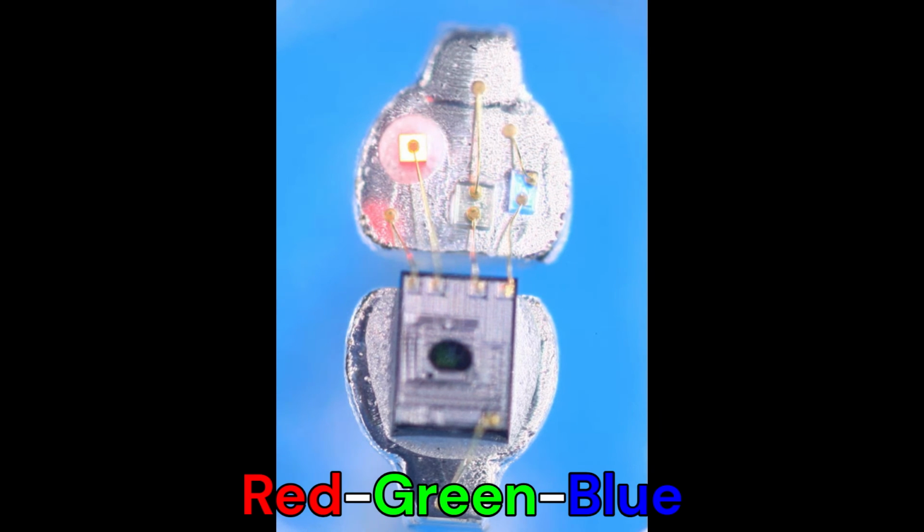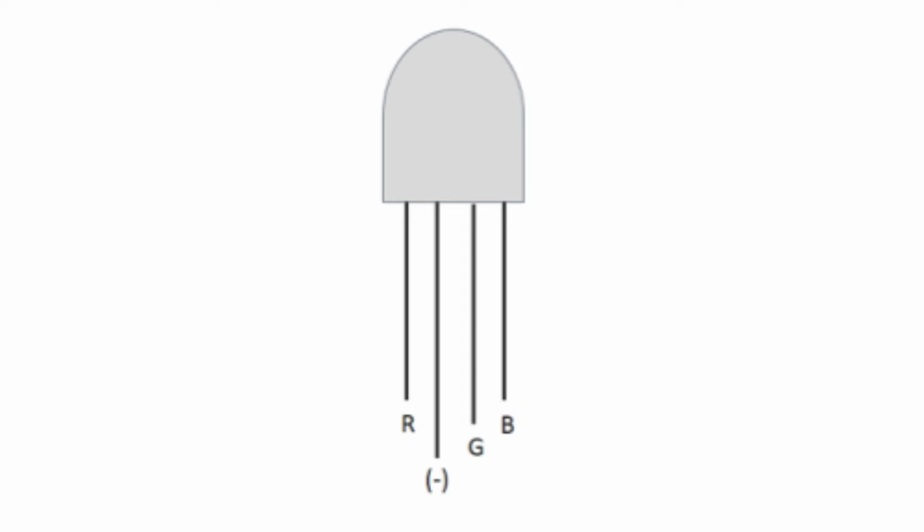The way RGB LEDs work is they have 3 different LEDs inside. A red one, a green one, and a blue one. And guess what? That's why they're called RGB. By mixing different amounts of light from these LEDs, they can make any color in the visible color spectrum. And that's why they have 4 pins: a ground pin, like for normal LEDs, and then 1 pin for each LED, red, green, and blue.